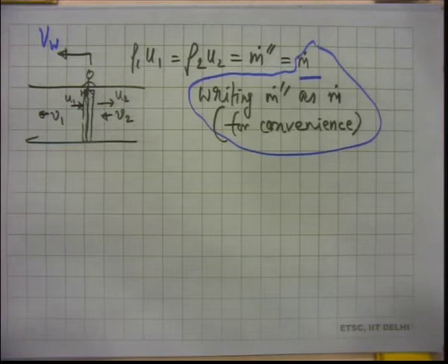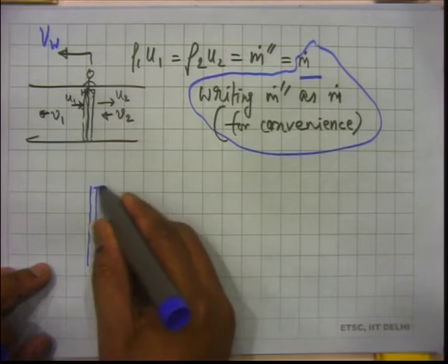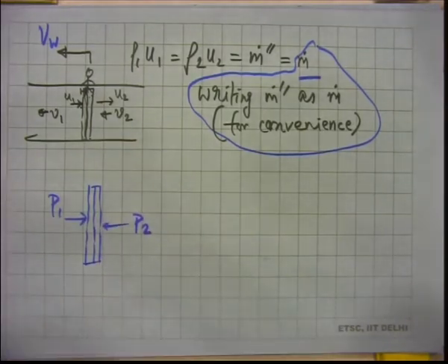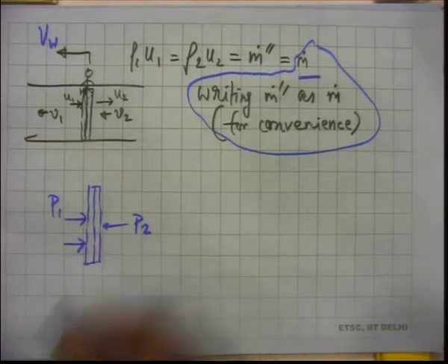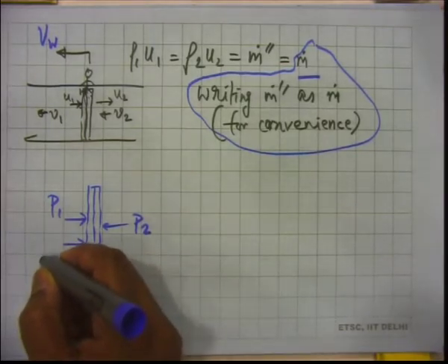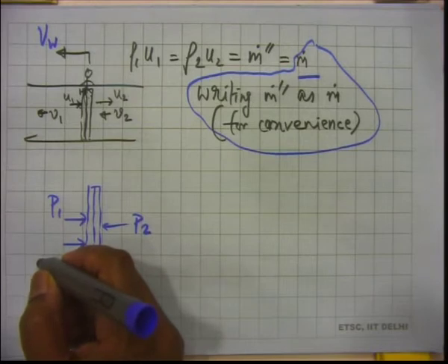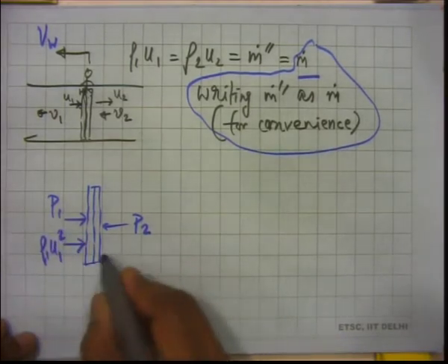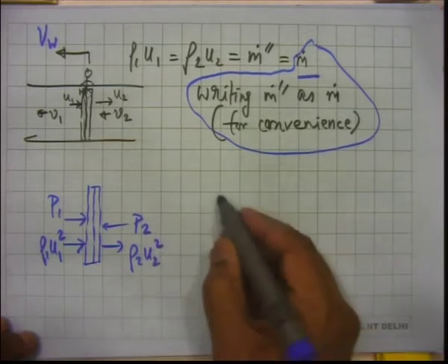Now, if you again take this combustion wave, and if you take this control volume here, then there is P1 acting on this pressure and P2 acting on this. So this P1 minus P2 is resulting in some change in momentum. Okay. What's the momentum here? Momentum flux going into this. Momentum flux, mass flux is rho 1 U1. Mass flux going into this left face is rho 1 U1. So momentum flux should be rho 1 U1 square. So this rho 1 U1 square going in, and there is rho 2 U2 squared going out. So we should be able to write